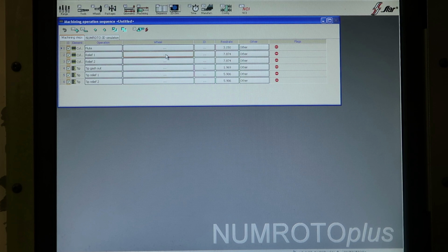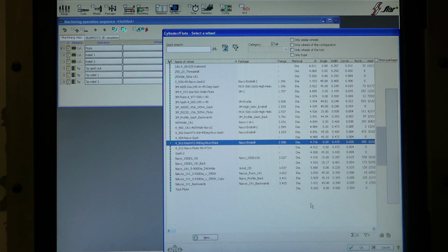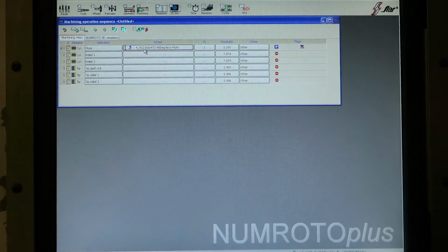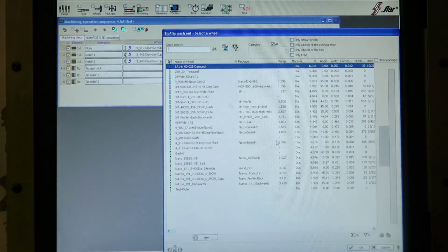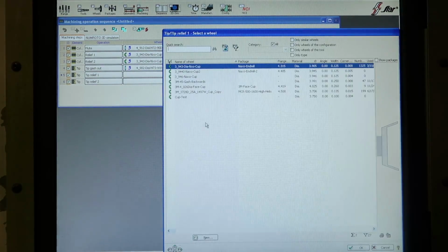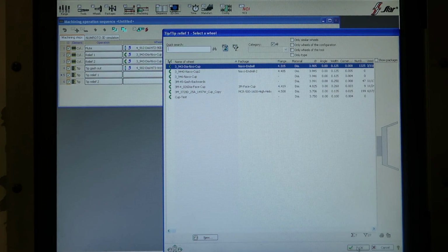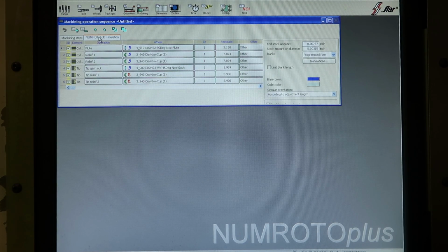It's defined all of these shapes for us. We're going to have to make changes to some of this, but we have to select grinding wheels. So for the fluting, I'm going to select that wheel, and we're going to say OK for that wheel. This is all on a grinding wheel pack already that I'm selecting. All these wheels are on one arbor already, which you'll see when we get to the grinding process. Okay, so these are the basic settings we have.